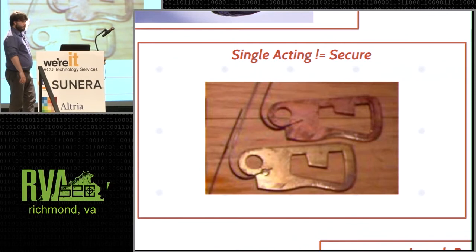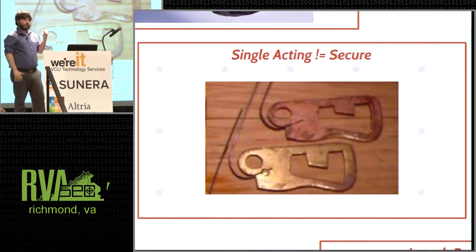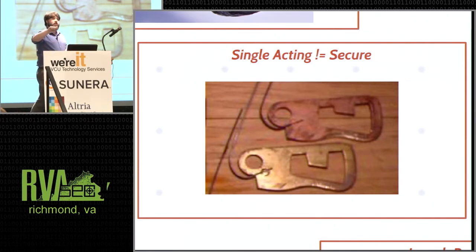where you can lift it up only so high, at which point it cuts you off. So that's cool, except that this now becomes incredibly easy to impression again. Because as soon as your key stops, remove a little material from it. See if it goes far enough, not far enough, remove a little material from it, and eventually you won't be lifting the lever up too high anymore, and the lever itself has told you exactly where the key needs to be cut to.